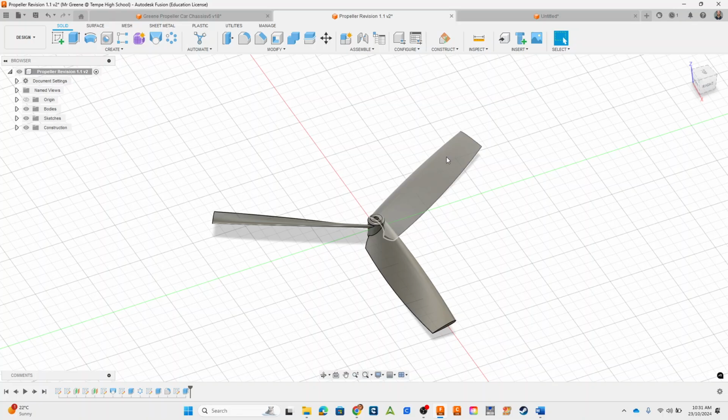So to iterate on this propeller, we're going at a curvature rate of 15 degrees. You might want to change that to 10. You might want to change it to 5. See what the difference in performance is in your different propellers, because that is a valid experiment. All you're doing is changing the design of the propeller. Okay, I'll answer questions at the end.